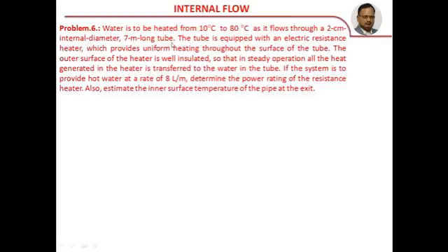See, because it is not a smooth pipe, we have gone for epsilon by d and so on. If you assume it as a smooth pipe for turbulent flow, you can use the other relation and calculate the power requirement. That power requirement will be much less than 508 kilowatts.